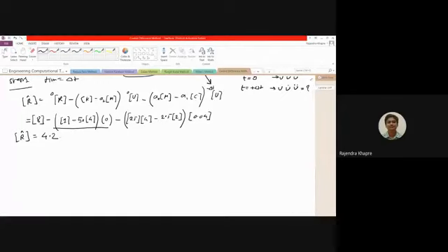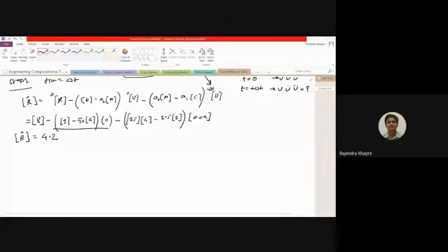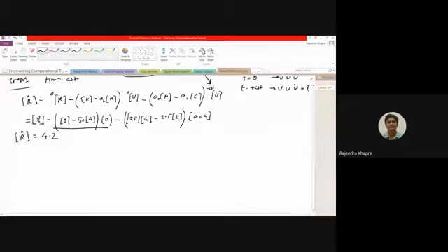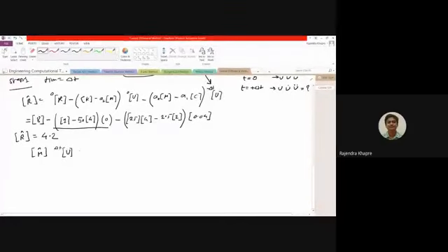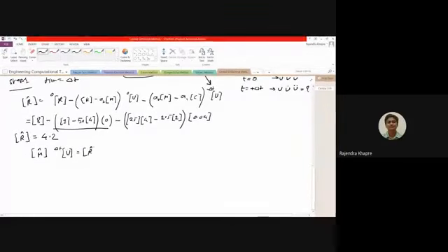Okay, so every time this R is going to change. So this is the first step. So we are calculating the response at time equal to delta t. So we have calculated the effective load vector R. So now we have to find out, first of all, the unknown displacement. To calculate the unknown displacement, we have a simplified expression: the effective mass matrix M multiplied by the displacement at delta t, which is unknown to us, equals the effective load vector R.